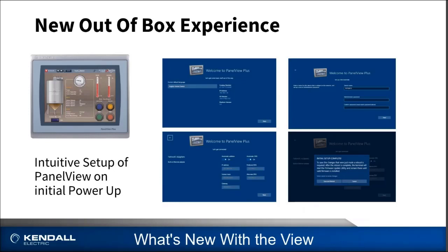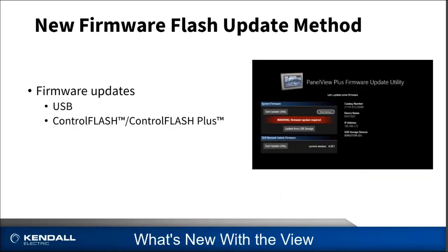So it'll allow you to do things such as set your preferred language, assign your admin password, set up the terminal IP address, etc. And so you step through the wizard, and at the end, it'll be all configured and ready to go. At that point, you're ready to flash the firmware of the unit. That's right, I said flash the firmware. So much like our PLCs, they ship from the factory with a base level firmware, and then you get to decide what firmware you'd like to put in it.